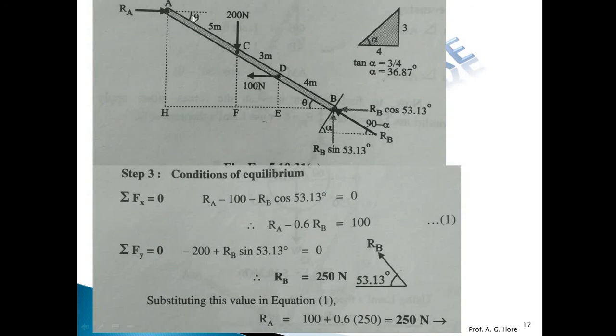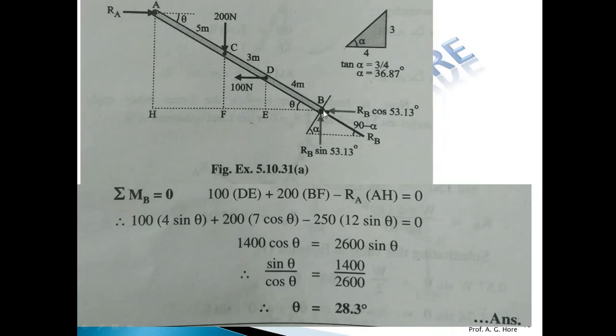Then theta is still left. So apply the third condition. Summation moment at B point is 0. Now here summation moment at B is 0. So RB is passing through B, so its moment is 0 because the perpendicular distance is 0. Now this force is vertical, this is horizontal. So for the horizontal force, this vertical is the perpendicular distance. For the vertical force, FB is the perpendicular distance, and for the horizontal RA, AH is the perpendicular distance. Okay, now